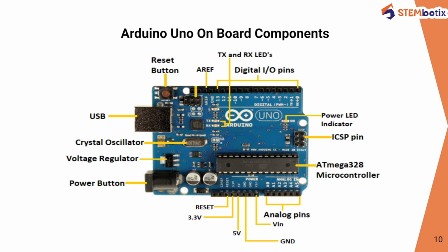These pins can read the signal from an analog sensor like a humidity sensor or temperature sensor and convert it into a digital value that can be read by the microprocessor. So the function of these 6 pins is to get the value of an analog sensor and convert it into digital, because your microprocessor can read digital values.